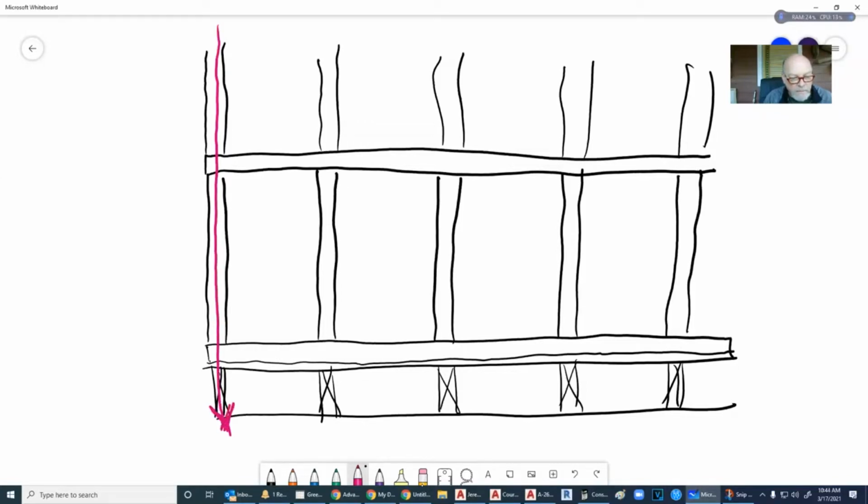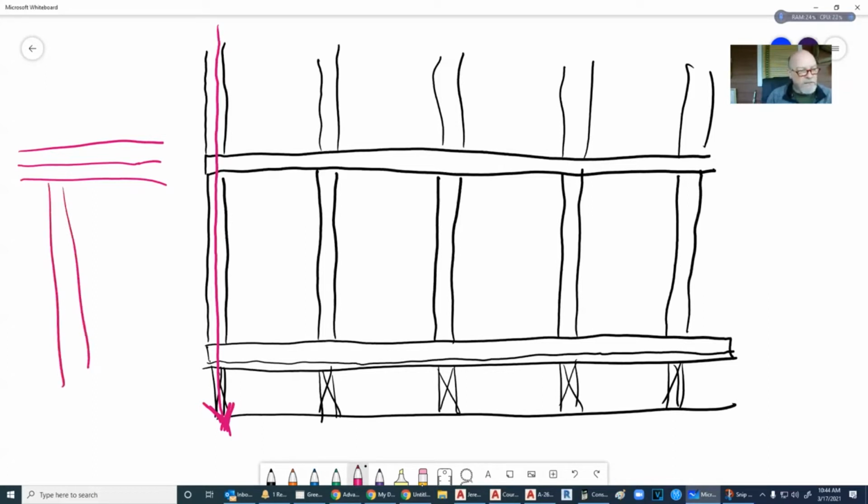through the entire building. So that's code acceptable as long as alignment's in place? Yes. Now, the reason that we put a double top plate is a couple of reasons. One, we tie the walls together, and two, it might be 16 inches on center studs, but then up here on the roof, it could be 19.2, it could be 24 inches.